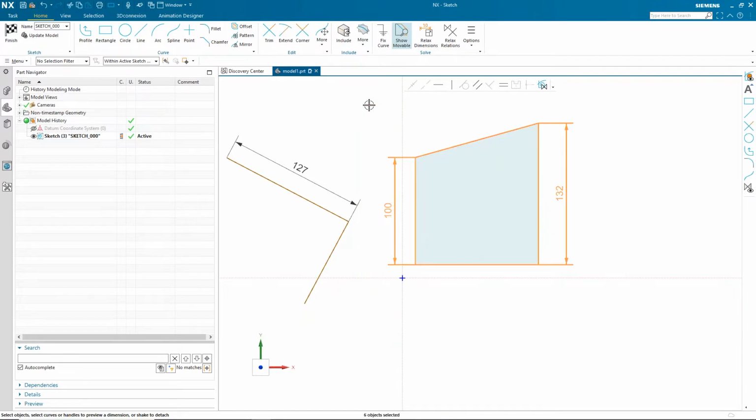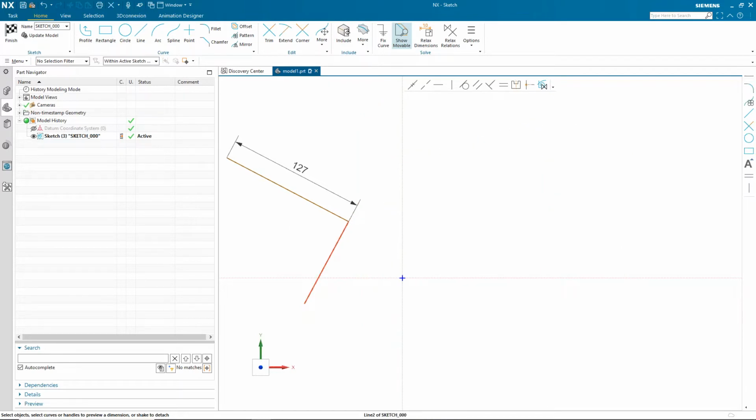So let me delete all these, in the interest of time. The other thing is I talked about shake and break. If I want to break these two lines apart, I pick this, hold down on this endpoint, and shake it 3 times with the mouse. 1, 2, 3. It comes off. It broke the horizontal, which is fine.